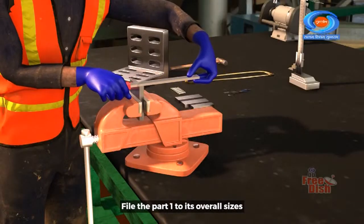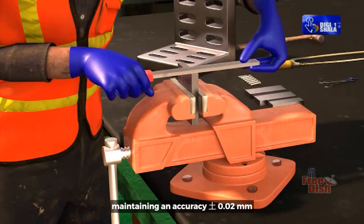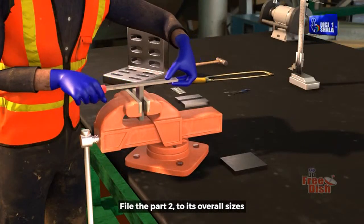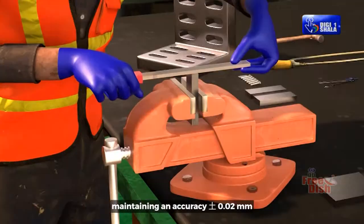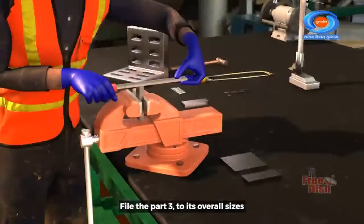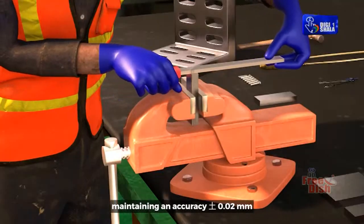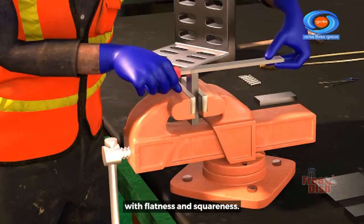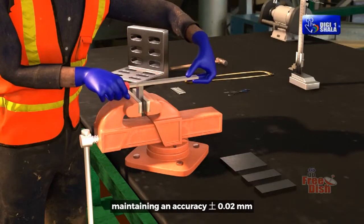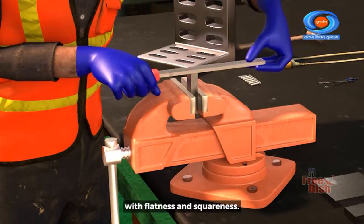File part 1 to its overall sizes, maintaining an accuracy of plus or minus 0.02 mm with flatness and squareness. File part 2 to its overall sizes, maintaining an accuracy of plus or minus 0.02 mm with flatness and squareness. File part 3 to its overall sizes, maintaining an accuracy of plus or minus 0.02 mm with flatness and squareness. File part 4 to its overall sizes, maintaining an accuracy of plus or minus 0.02 mm with flatness and squareness.